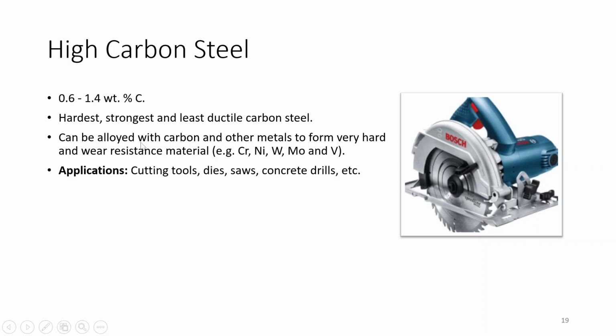When you add alloying elements for making tool steels, you add a lot of these types of metals, and these metals will form carbides. These carbides provide very high wear resistance. Applications include cutting tools, dies, saws, and concrete drills, etc.